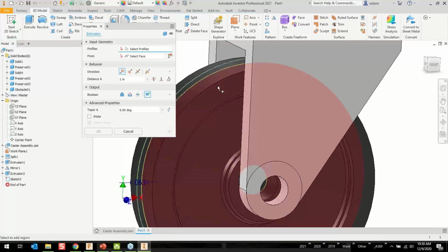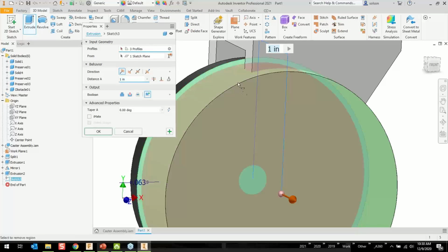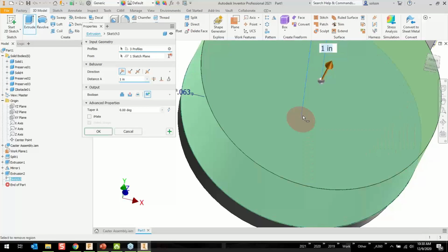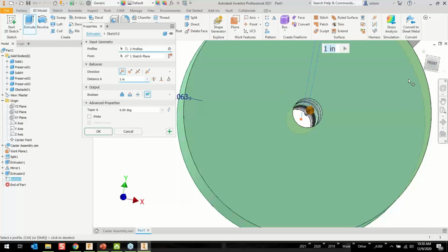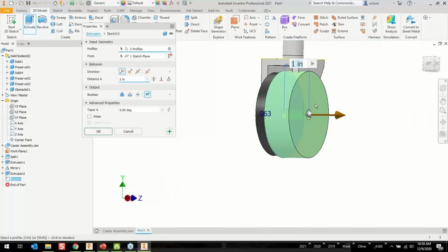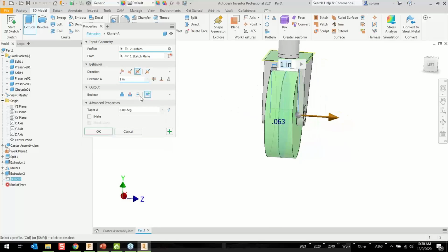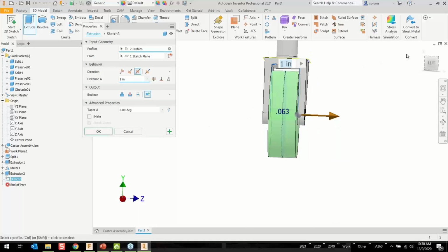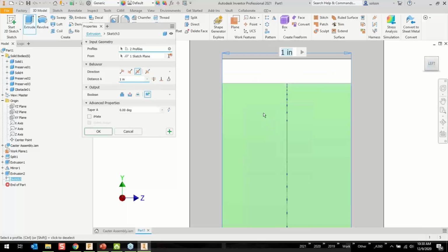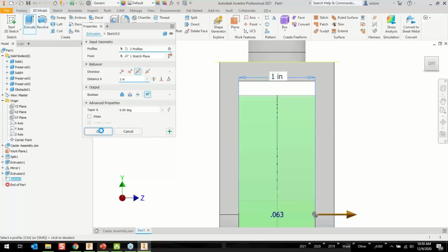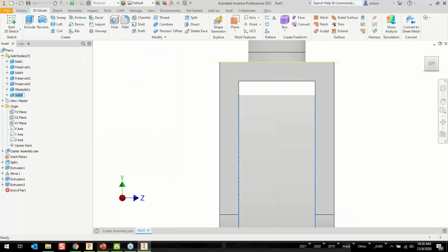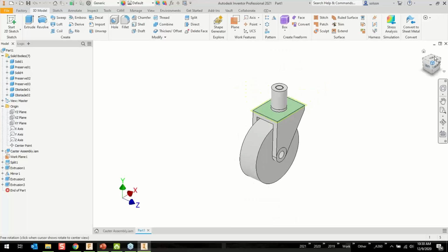One more extrude before we pass over to Fusion. I also want to get rid of that profile in the middle there. So I have basically the shape there that I need. I'm going to go off of midplane, 1 inch off of midplane, which will fill our gap. If you look there, it's going to fill that gap. Say it's a new solid. This will be obstacle 02. All right, so this is all that I need to do here in Inventor.